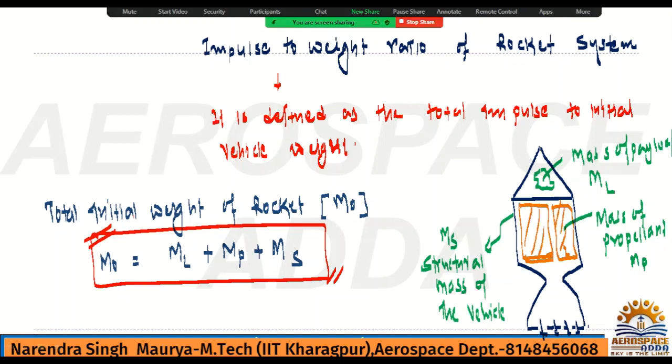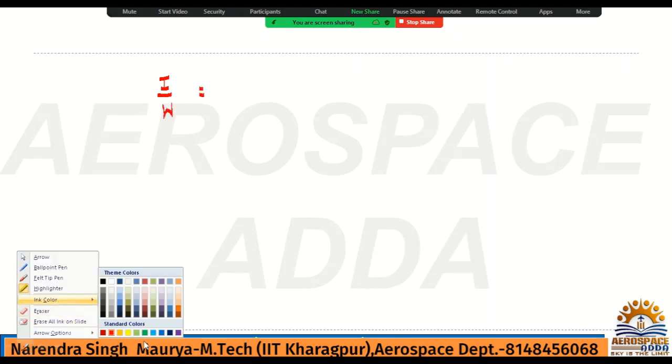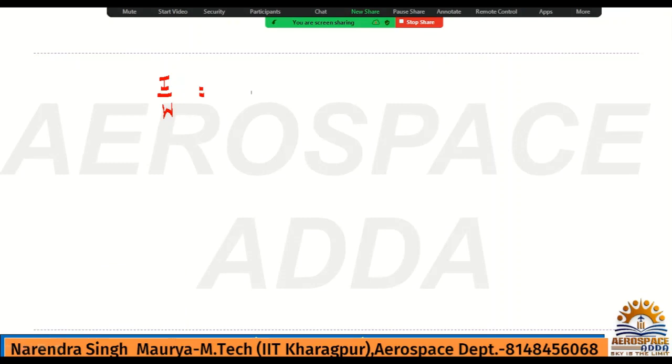So, impulse to weight ratio of a rocket system. What is the impulse to weight ratio? It is nothing but I by W, where I is the total impulse, IT, divided by the total weight, which is the initial vehicle weight. So what is the initial vehicle weight? I can write W naught.